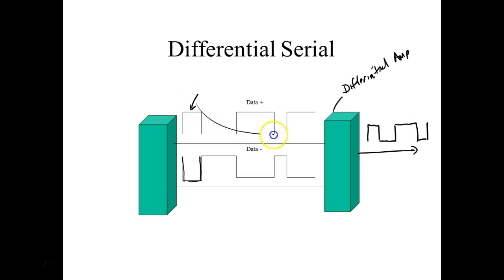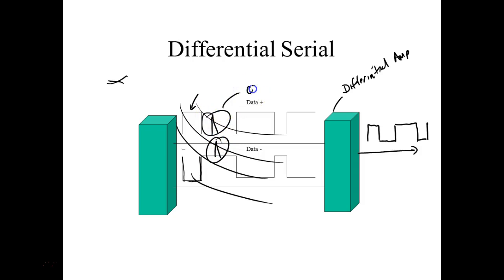Now what happens, we have a magnetic line of force that comes through here. We use what we call twisted pair cable, which means that your two wires are twisted together. Then if you induce a signal into this one, you're going to induce the same signal into that one. Well, the problem is that this is no longer differential. We call this common mode. So what the differential amplifier does is it rejects common mode signals and only lets differential signals pass through.